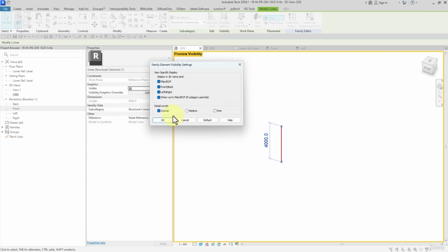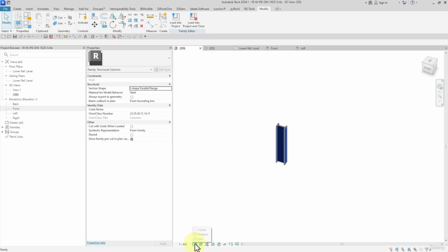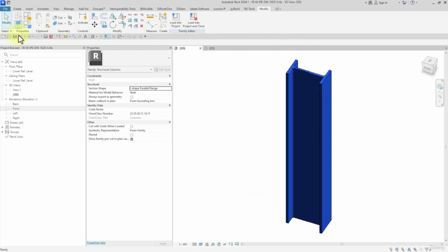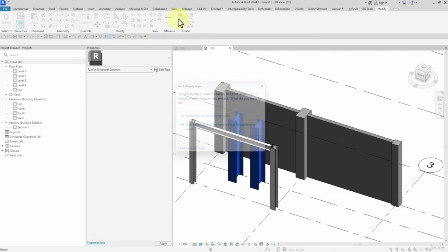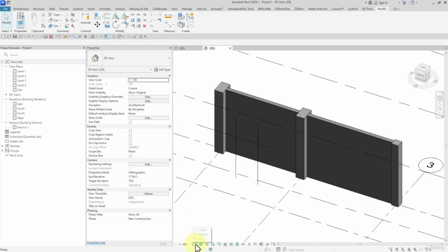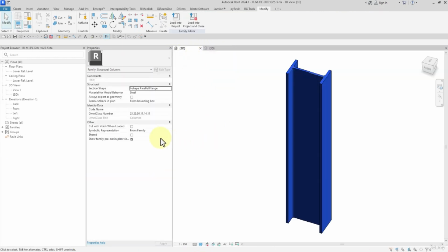I selected opening the visibility settings only in coarse. I keep checked coarse. Then I save the file. Turning off the preview, fine. Watch this, save. If I load this into the project, overriding the existing version and its parameters, coarse, watch the lines, medium, and fine by display.